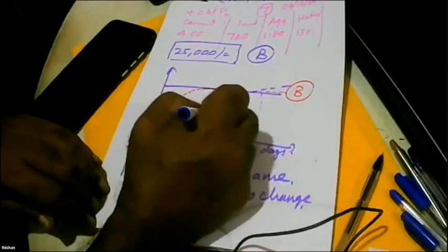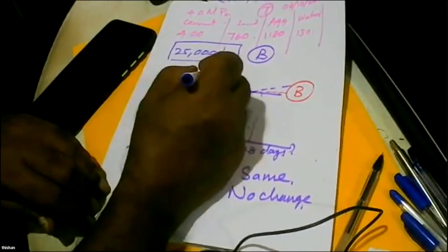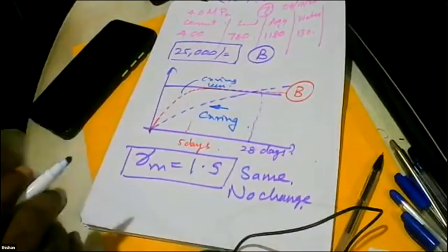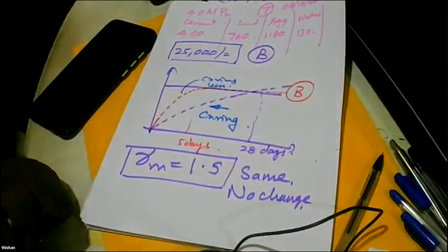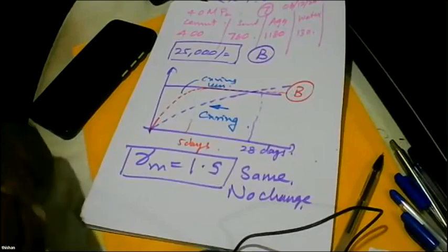Because for this one, curing is very important. This one, curing is less important, but the durability of this concrete will be lesser. Why? Fly ash will give chloride resistance, fly ash will give sulfate resistance, fly ash will also give a dense crust or dense cover zone. So which is better then? B is better.